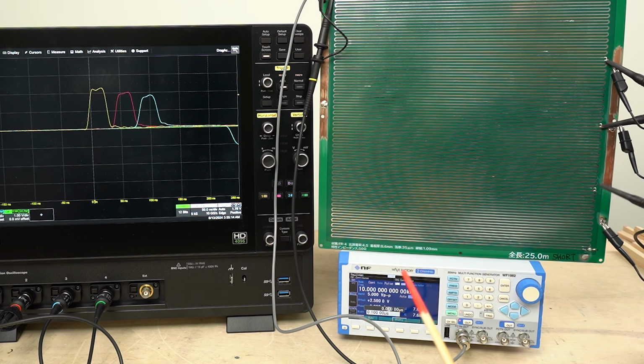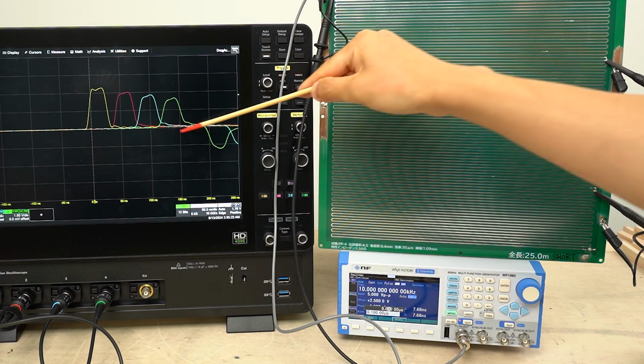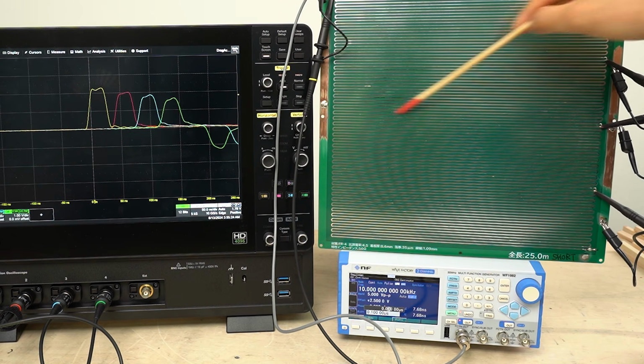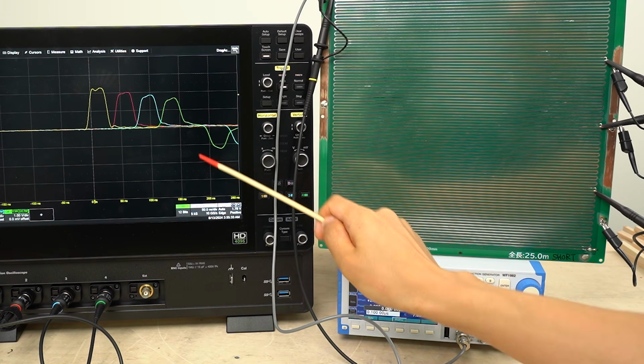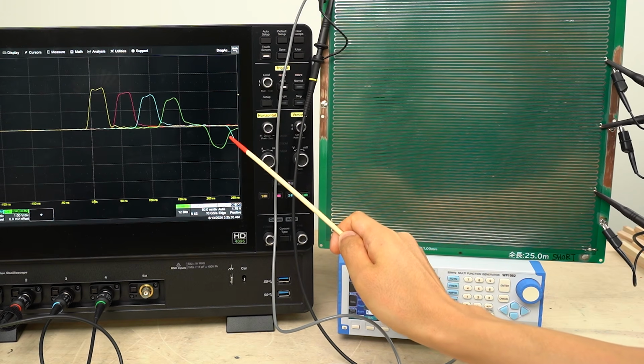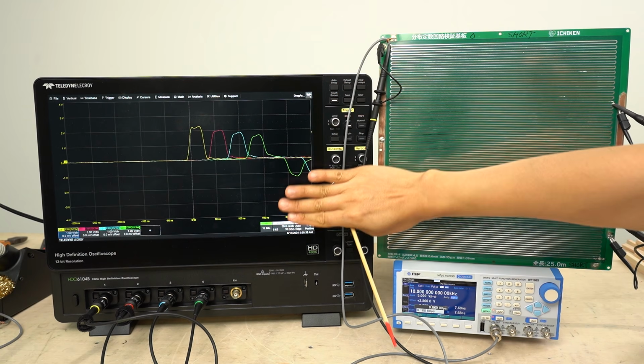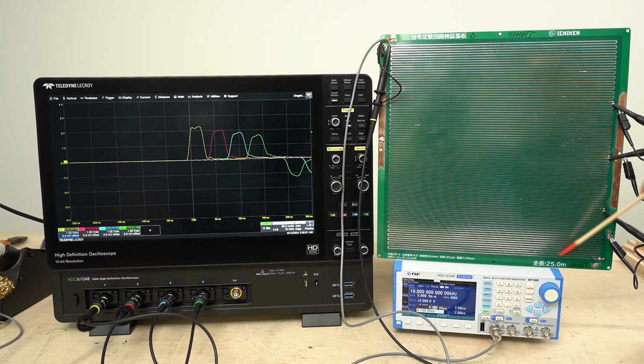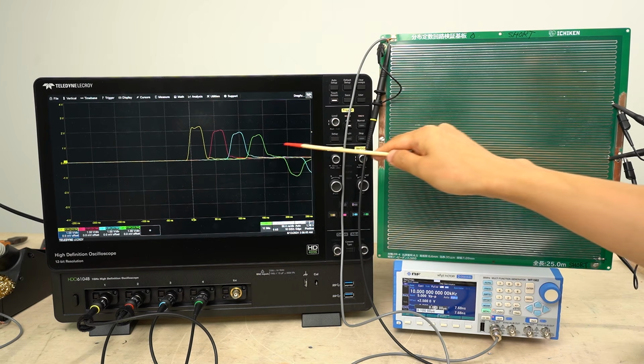Next, let's move on to the 75% point. The incident wave still looks the same at this point. But take a look at this. The waveform here looks quite different from what we saw in the open-end case. The waveform is flipped like this. This is the reflected voltage after reaching the short-circuited end, and it's negative.